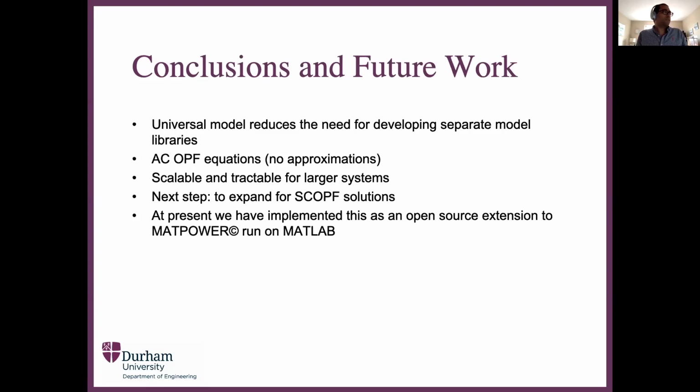The next immediate step is for us to test this on a potentially larger scope problem, security constraint optimal power flow, which is another layer of complexity on the normal OPF. We have implemented this model as an open source extension in MATPOWER.